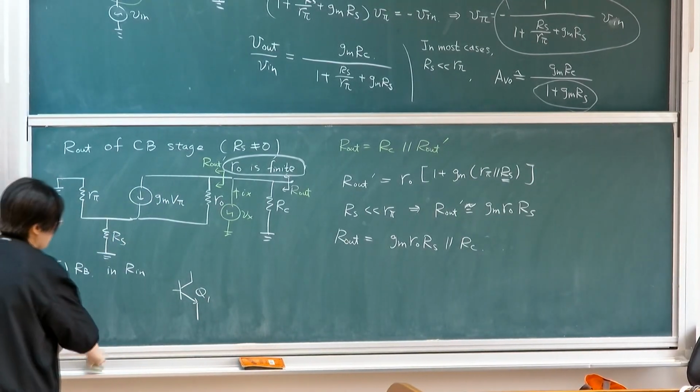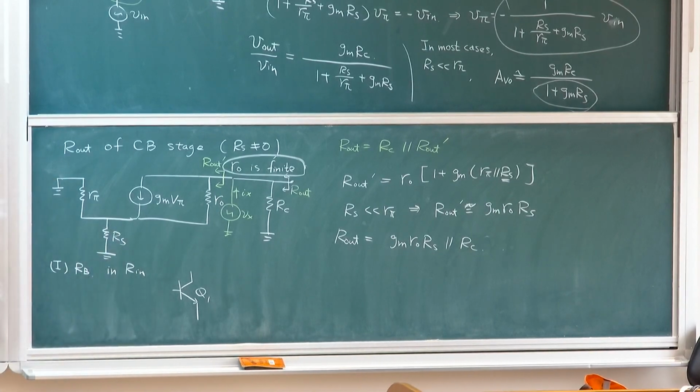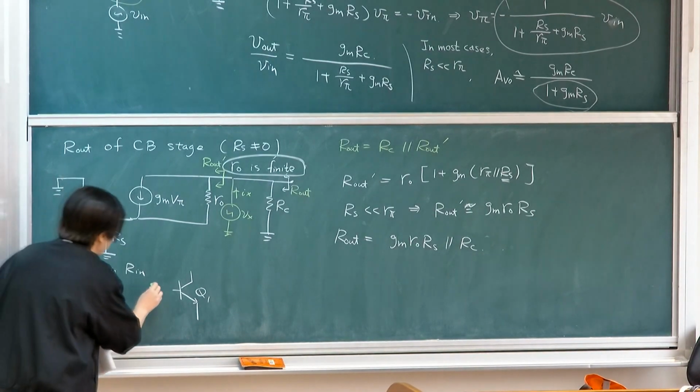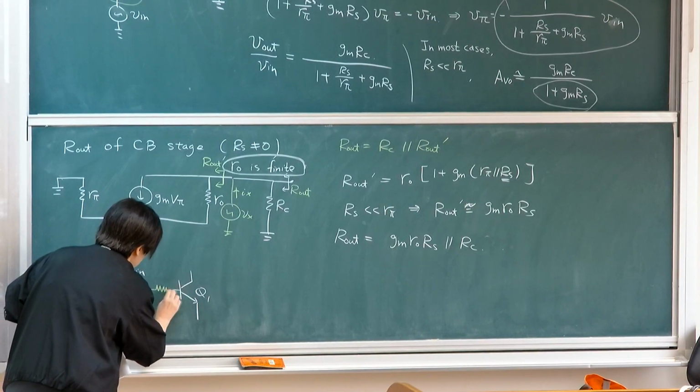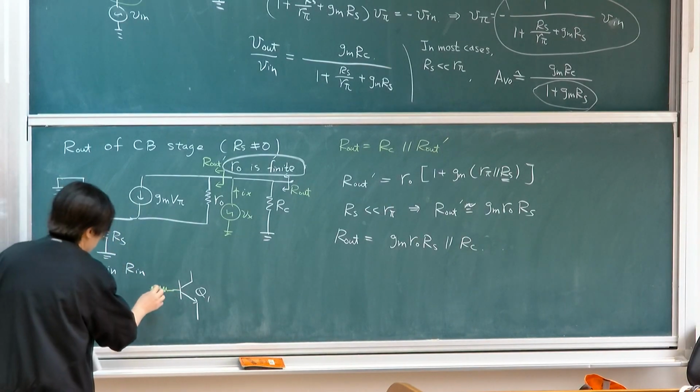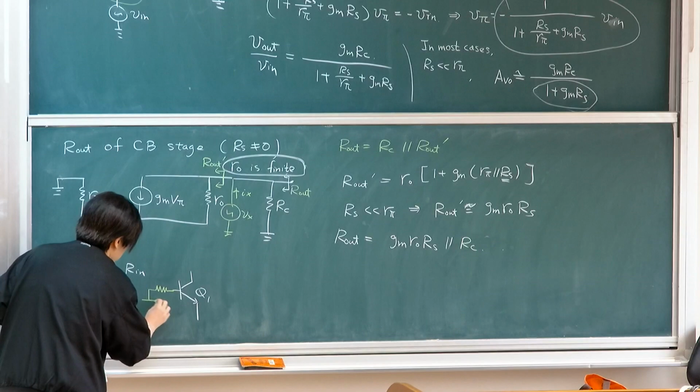What I meant by this is that, assuming my base is connected to a voltage source, the voltage source will actually have source resistance or resistance of 0. So what if my base is connecting to a wire, so there might be parasitic base resistance? Let's say my circuit looks something more like this.